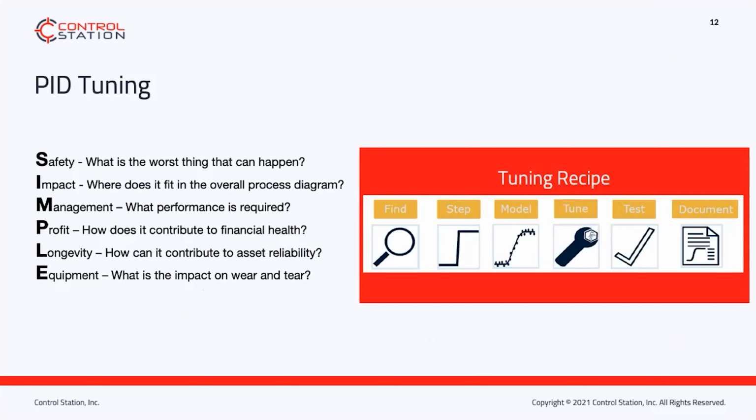So step 4 is tuning the controller. You need to convert the controller gain and time constant to fit with the controller on your facility. The information needed should be in the controller manual. Next, you test your tuning and you document the work.